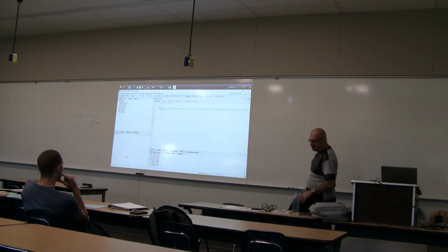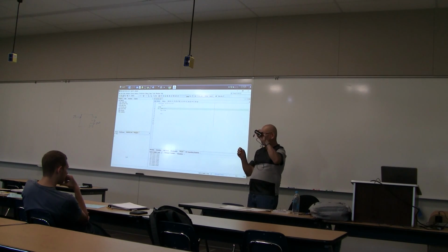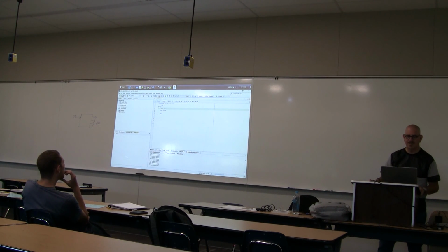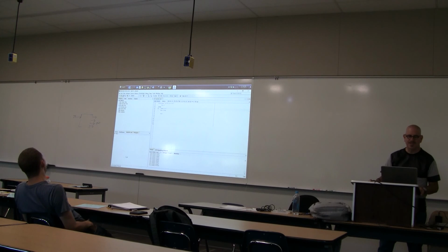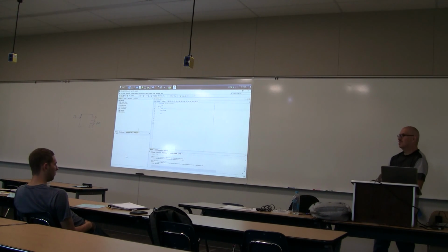Now, if I was satisfied with this program and it was doing something useful, I'd hook this up, I'd connect the chip to these 5 wires coming out of here, and then when I want to program, I'd stop my simulator, I would say build my main project. And then I would have a little option down here. There's a little downward pointing arrow, and if I click on that, with this thing connected, it will take my program, push it through that programmer, and load it into the chip. And then it starts executing on my chip, and it's doing whatever I told it to do.